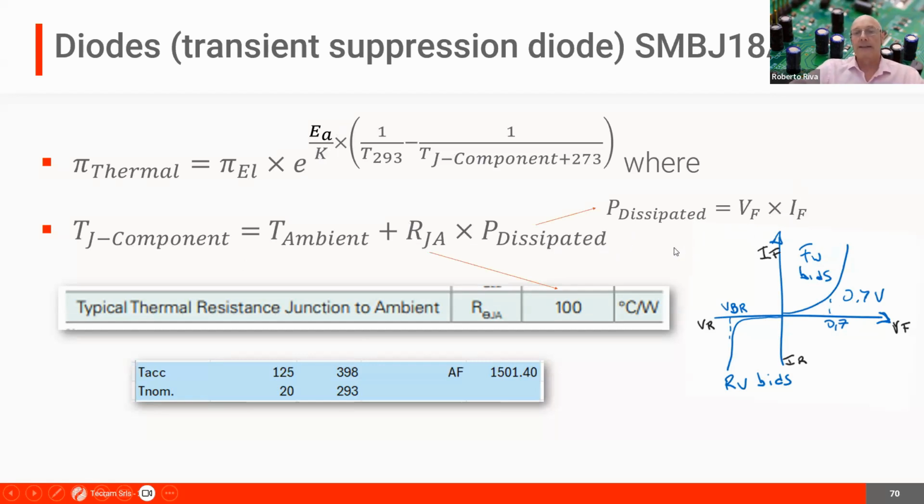But we are stuck on this, and therefore we get to the end of the buffer basically, and we can't go any further. So we assume this is 1 watt, and that is basically multiplied by 100. This pi L was the one that was really causing all the problems, because there is another formula behind it. It's not just a simple number, and that was the formula that was blocking us from inserting the diode settings, the 12 volt and the 18 volt settings, because by selecting a transient suppression diode, it was basically erasing the possibility, setting this to 1 and removing the formula altogether, and therefore we couldn't set this value of the voltage.